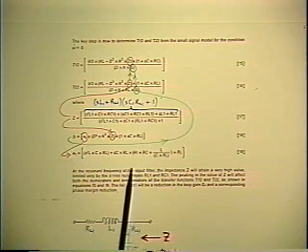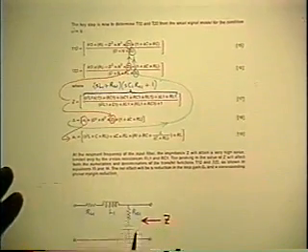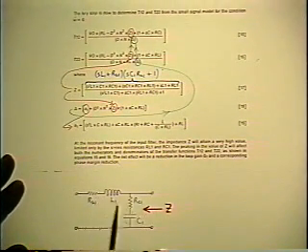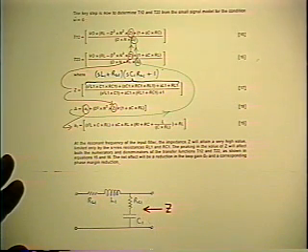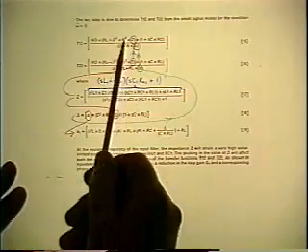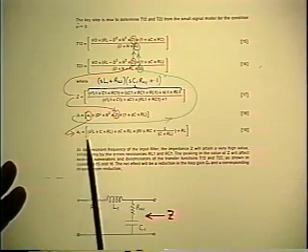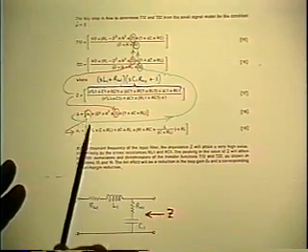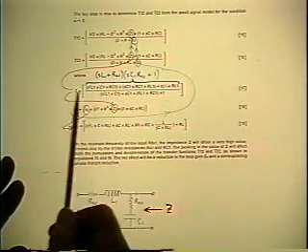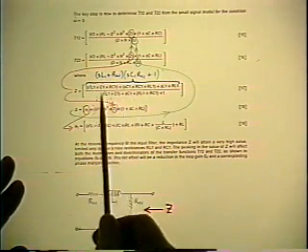And here is one page out of a manuscript that I got not too long ago. It's to do with the output impedance of a damped LC filter, exactly the one we've been talking about, except a little simpler. It has the ESR there, but not the load. And this is the algebra that appears in the paper. Now these T's are various loop gains, and it doesn't matter much what they are. The thing to look at right now is this one. This Z is the output impedance of that network. And see how he's written it.